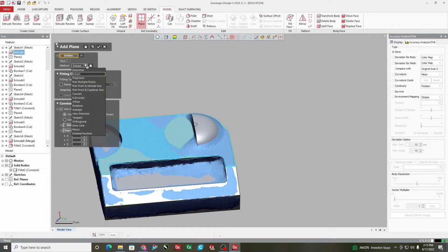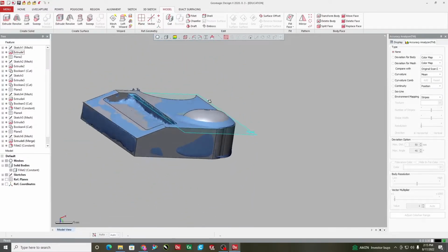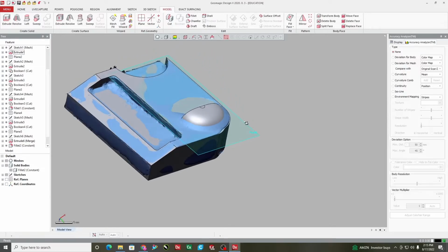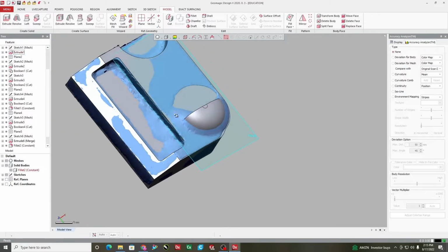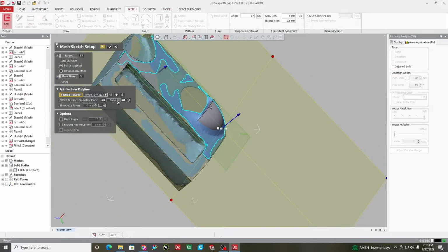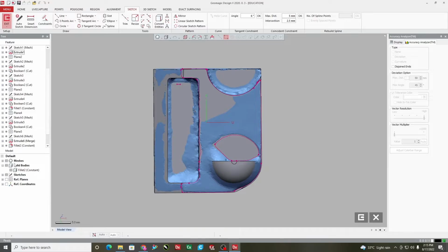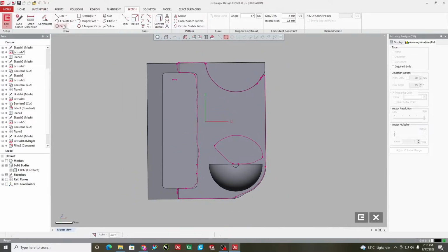So now I need to create the dome cavity. I'll again add a plane. I'll select a plane. I'll pick multiple points on the plane. On the top of the, we will create a plane. Now I'll again create a plane on the surface. This plane is generated. So this is plane 6. It is also showing the number of the plane. It keeps on adding the commands, the planes that we are generating. So now this is the plane that is generated, and also we have got the outer line of the cavity.